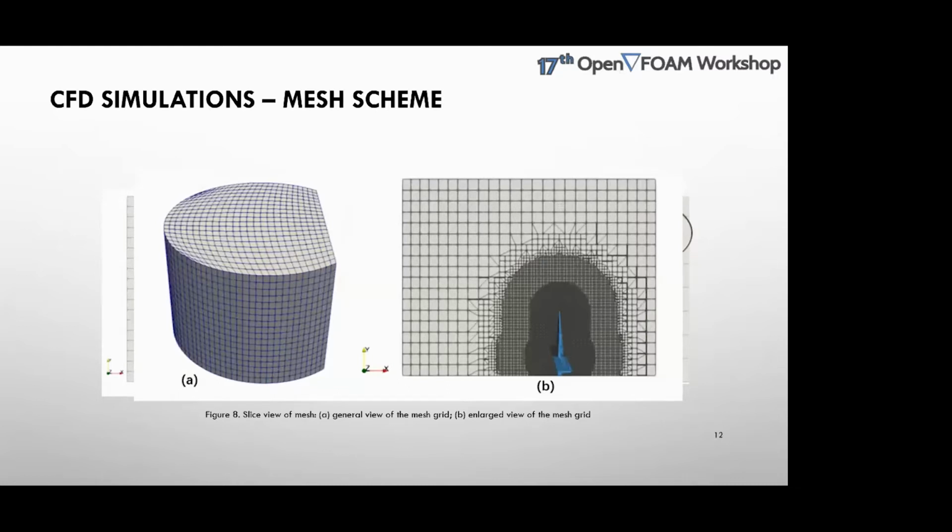Here is how it looks for the cylinder mesh scheme. You can see from the top faces, the blockMesh cuts the domain in an arc way rather than a straight line. So in my opinion, it's not the best way to generate the mesh, because there is an increasing risk of generating bad meshes in key areas, especially after changing the yaw angles.